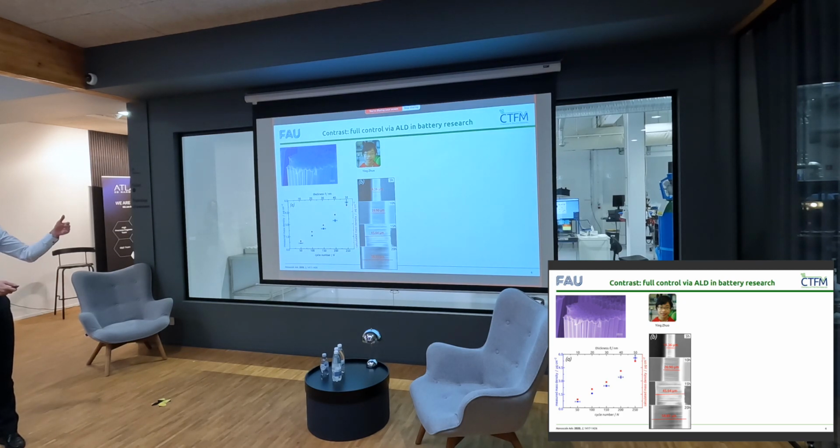So this is an example in battery research, and we've heard more on that than we are capable of doing. But this shows the structures. Of course, these have been removed out of the matrix just for the purpose of taking the image, but typically we keep them inside the matrix. And if you vary the number of ALD cycles that you perform, maintaining the pore length constant, then you can calculate, of course, that the loading should increase linearly. And if you actually measure the mass, then you see that it does increase linearly.